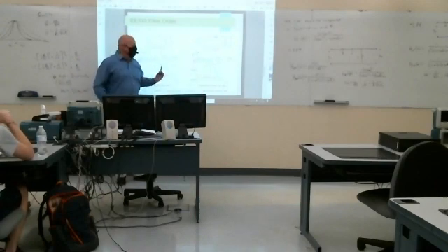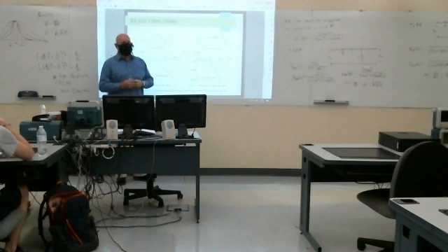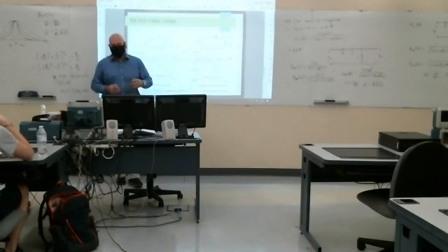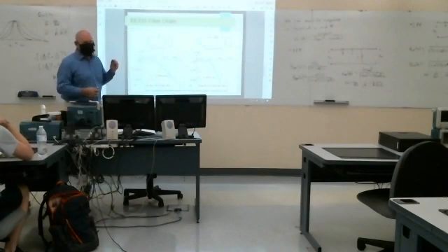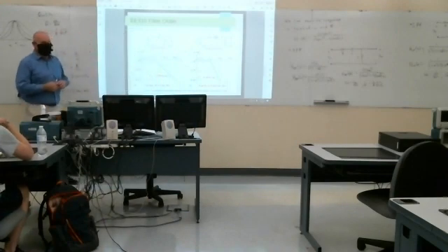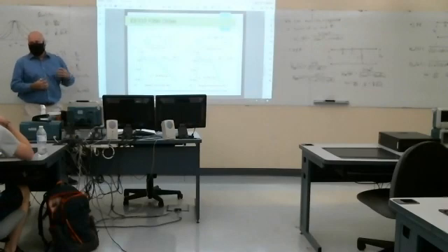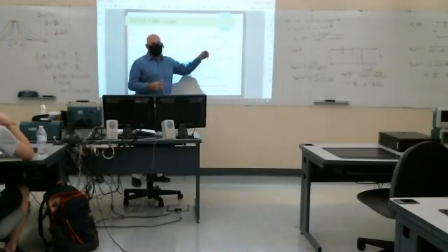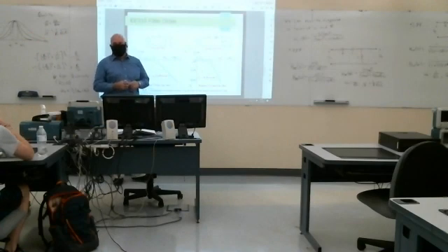And again, at audio frequencies, inductors tend to be large and heavy, so generally we try to avoid them. At radio frequencies, inductors can be pretty small, just a few loops of wire. But at audio frequencies, the inductors we work with that get any appreciable impedance have to be fairly large compared to the capacitances.